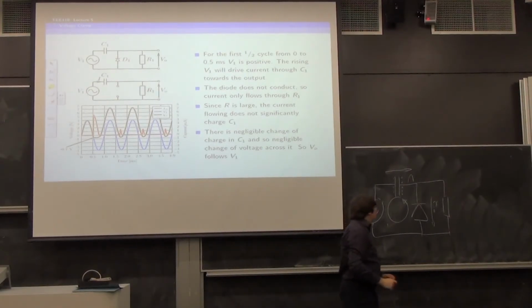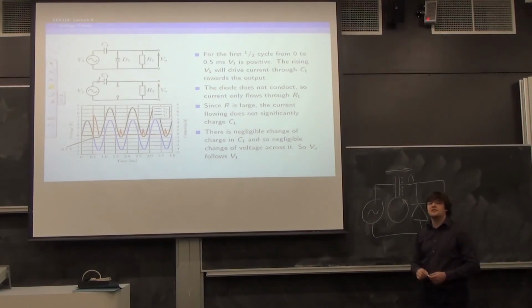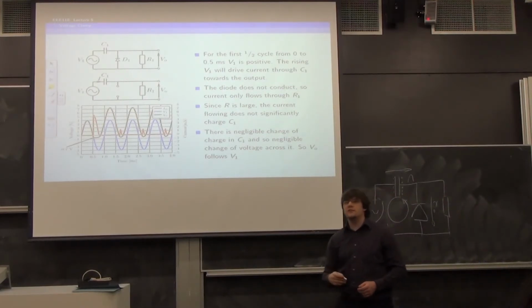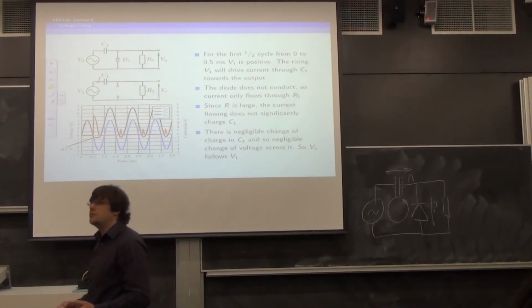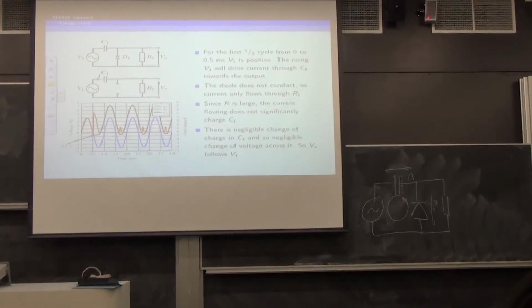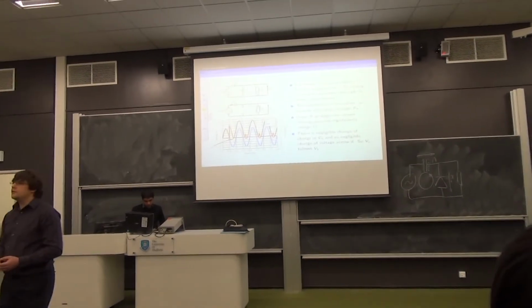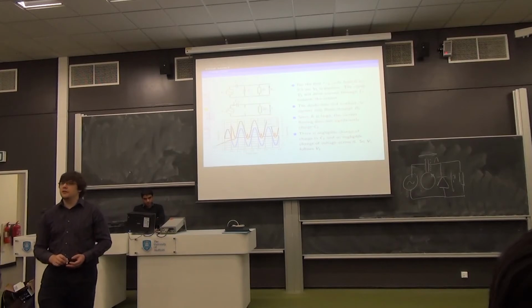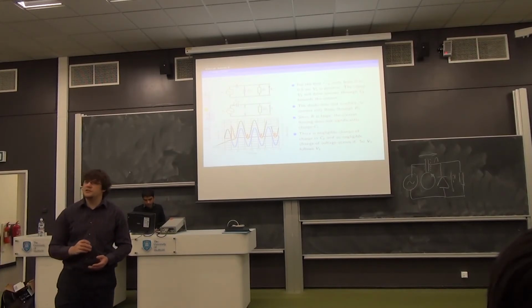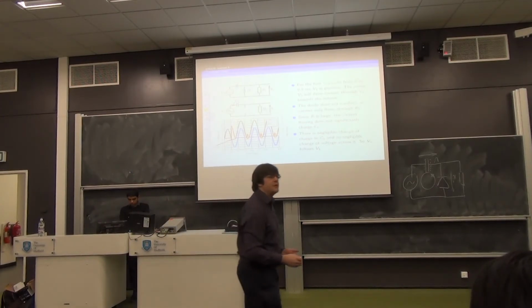And at some later point, oh there it is, the diode will cease conducting, and it will cease conducting because there will be no more current flowing into the capacitor. The capacitor will become as charged up as it can be, given the voltages which surround it. So the current will cease, and that will cause the diode to switch off. It is not a case that the voltages become such that the diode switches off. It's the capacitor finishes charging up as much as it can, the current ceases, and that is the switch off of the diode.